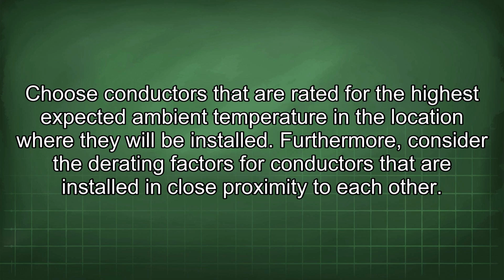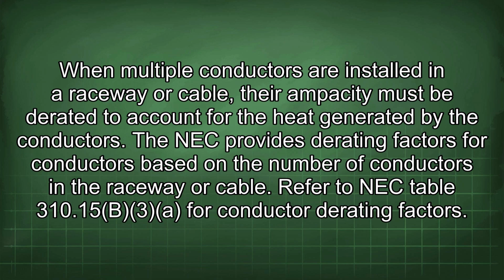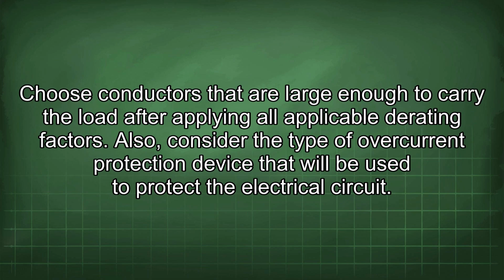Furthermore, consider the derating factors for conductors that are installed in close proximity to each other. When multiple conductors are installed in a raceway or cable, their ampacity must be derated to account for the heat generated by the conductors. The NEC provides derating factors for conductors based on the number of conductors in the raceway or cable. Refer to NEC Table 310.15(B)(3) for conductor derating factors. Choose conductors that are large enough to carry the load after applying all applicable derating factors.